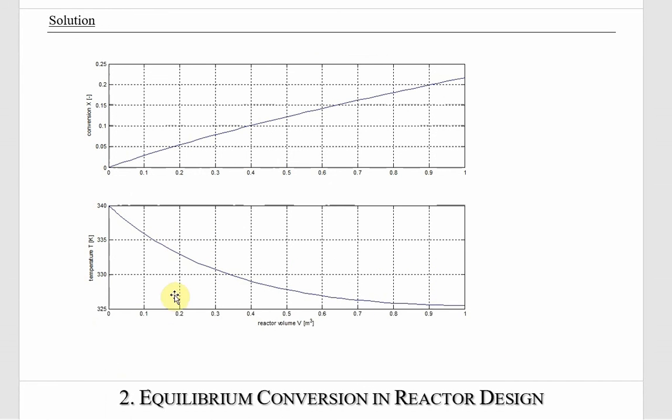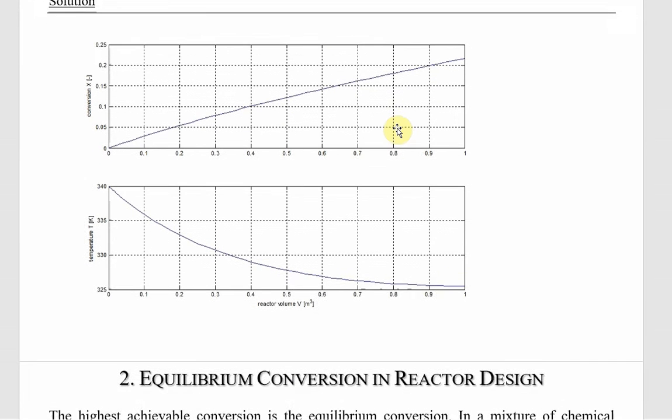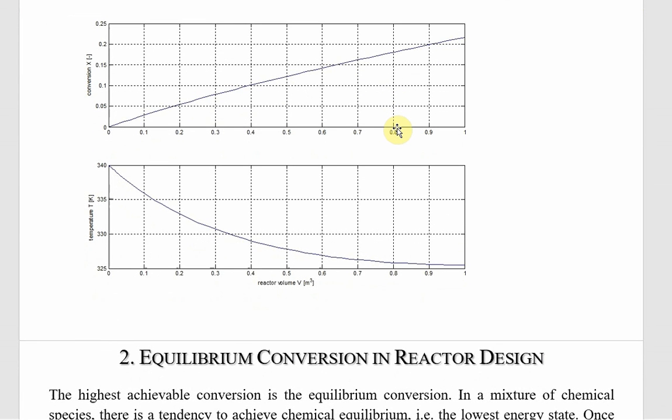So the reaction rate is going down pretty fast, and so the conversion doesn't rise as rapidly as we've seen in the previous examples. Of course, that's all dependent on the choices of constants that we used, but I didn't really change the constants from those previous examples. In the previous examples, we got conversions on the order of 60 odd percent, and now for similar values, we aren't seeing as high conversions. So you can see that the temperature does play a significant role in this whole business.